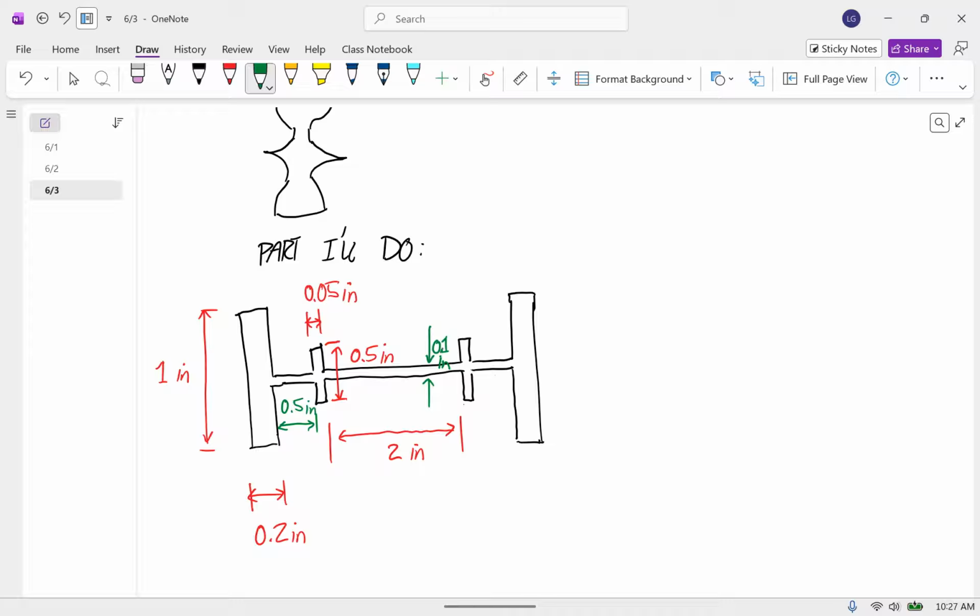All right, so we're going to use a revolve tool to do this because this is symmetric about the axle itself. Everything here is circular. I'm just telling you that. You can't tell from that picture what those shapes are, but this is a circle, this is a circle, the axle is a circle.